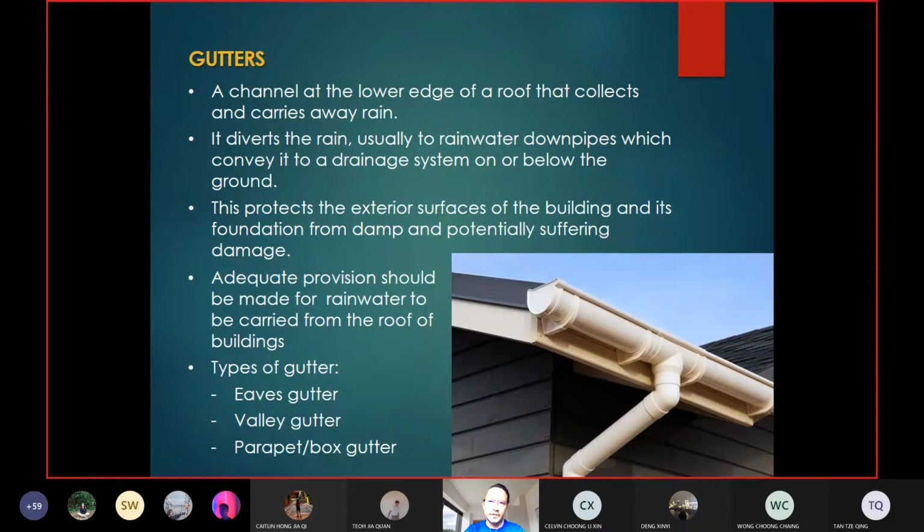But of course, for the initial design, you need to have some idea. So in your design, you cannot have very few downpipes. For example, you have a very huge roof that covers the whole building, and you only have one downpipe. That is not logical. So you need to provide several, maybe 3 on each side. You have 3 downpipes, so 3 go to the back and 3 go to the front, or something like that.